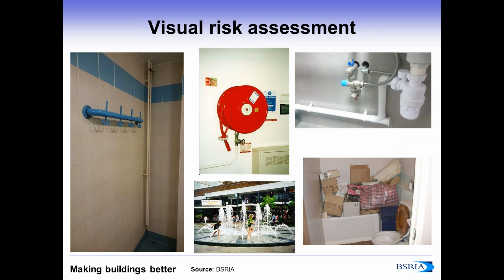The top photo in the middle is a wet fire hose well. This could be a reservoir for bacterial growth and would put at risk the person testing the firefighting system during maintenance. You could note that the risk of contamination in case of fire will be minute, as most of the occupants should have already evacuated the building when the spray of water occurs.